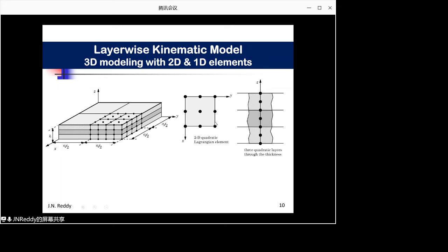For a thick laminate, that will not happen. Each top layer and bottom layer will experience more stress and the middle layer has no stress. Whereas the first order shear deformation theory and classical plate theory predict linear variation, because that's what we have in the displacement field, and they are doing the best they can. But in the process, what is it they are doing? They are approximating this curve in an average sense. Okay? And in the process, they also predict a jump at the interfaces.